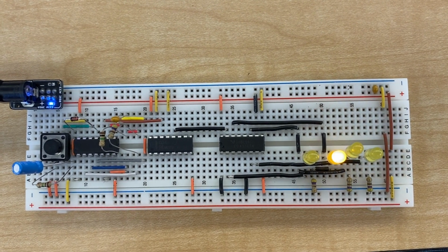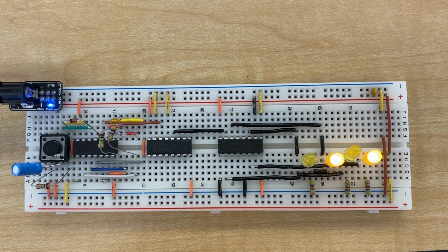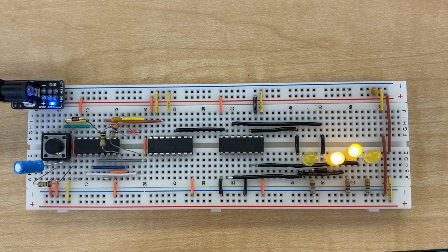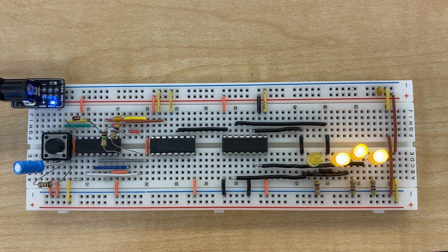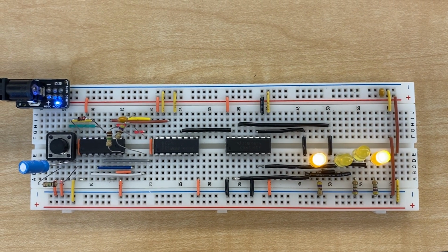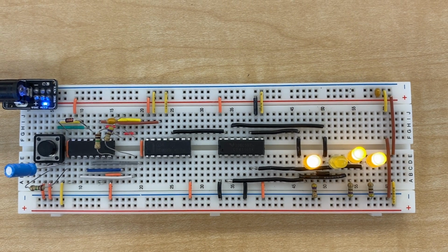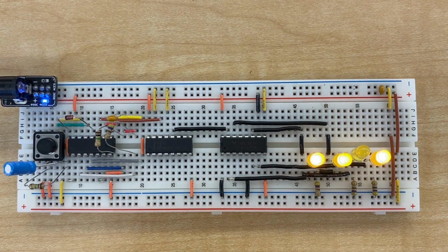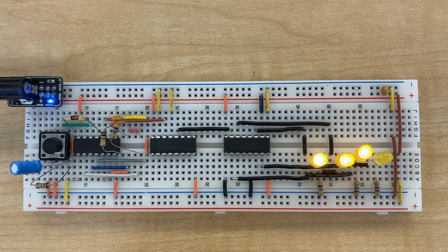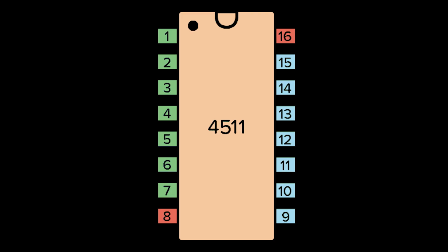This counter counts from 0 to 9 or 0 to 16 in binary and with 4 outputs and uses the 4510 or 4516 chip. This chip also has an up and down option for the counting, which is implemented in the final PCB. The last chip is the 4511.